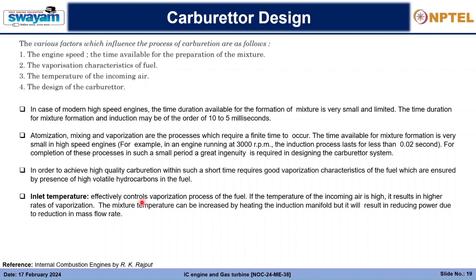And at cold start, what happens is that in very cold countries, you will find the engine does not start very easily. Why? Because the temperature of the system is not high enough to completely vaporize the fuel. The fuel is still in liquid form in the charge which is passed onto the cylinder. And when the liquid form of the fuel is passed, it does not ignite. If it does not ignite, it will not add the heat energy, and no work will be produced.